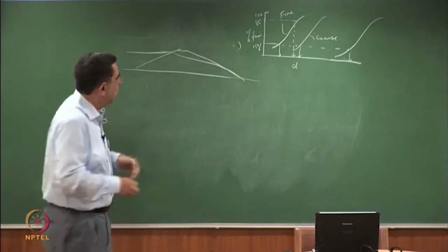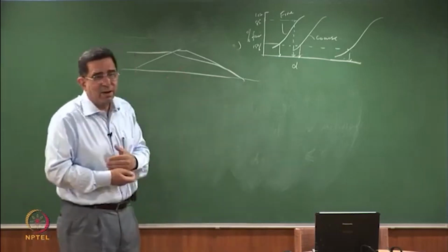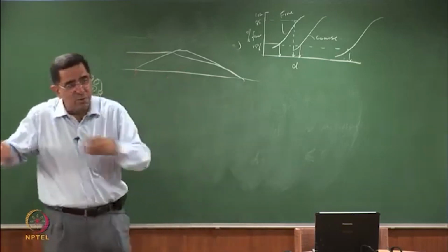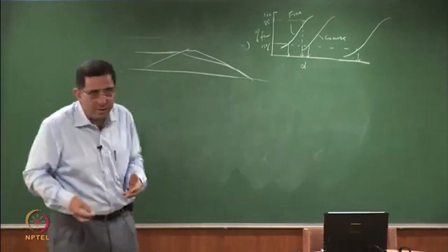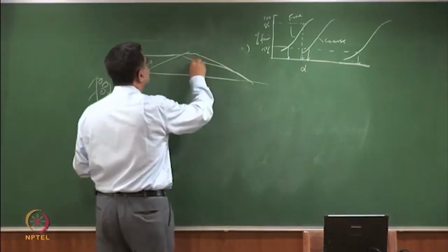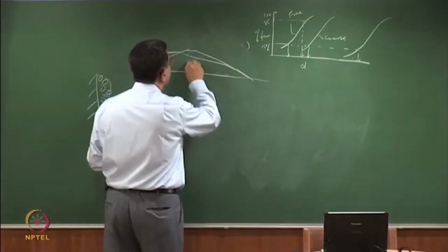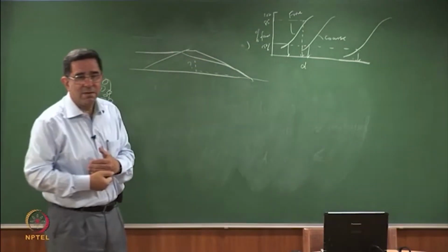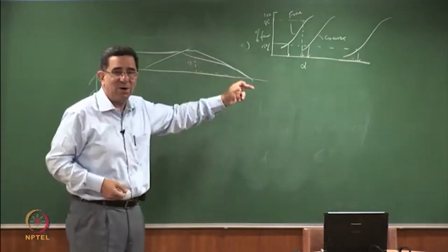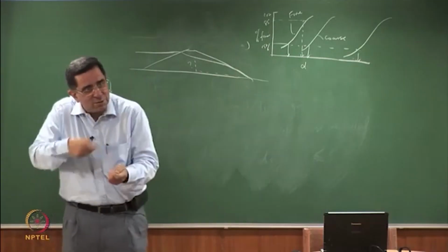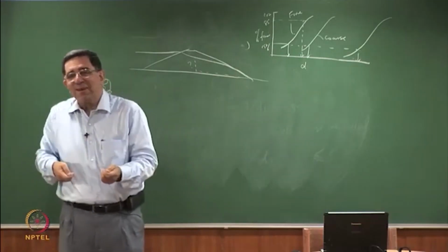Well, one thought is let me go and make a chimney drain inside. Now the pond is working, there is water behind it. How do you make a chimney drain? How do you make a blanket drain? Can I make this? Not possible. Maybe I can make a vertical trench, but this is just definitely not possible. Maybe I can drill some horizontal holes to make the drainage.